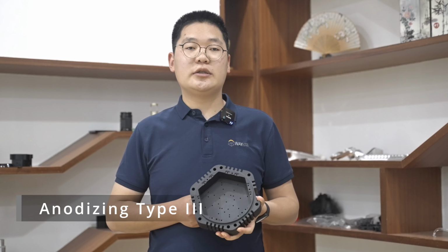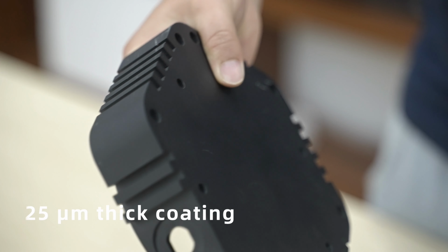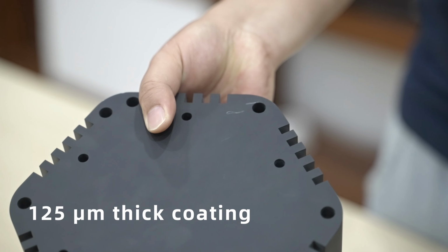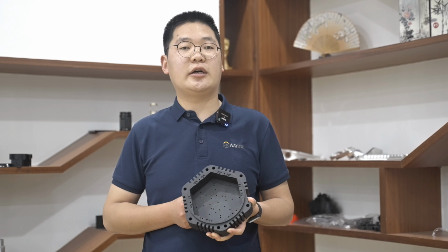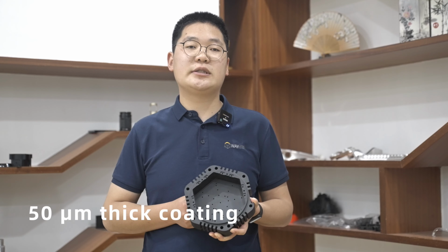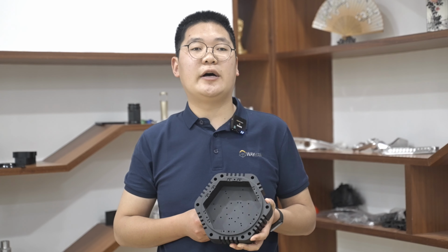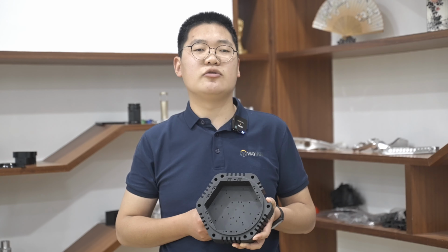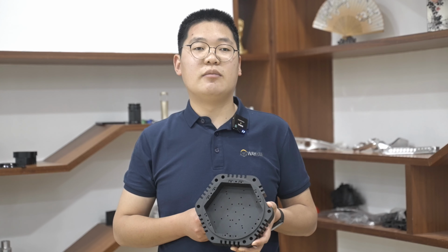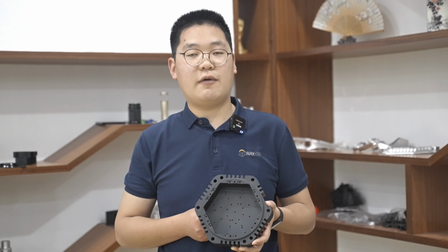Anodizing type III, also called hard coat anodizing, can produce coating up to 125 micrometers thick. If not specified, the typical type III anodized coating is 50 micrometers thick. The cost of anodized type III is higher than that of anodized type II because it requires close process control. Type III anodizing is the most expensive out of all finishes covered in this video.